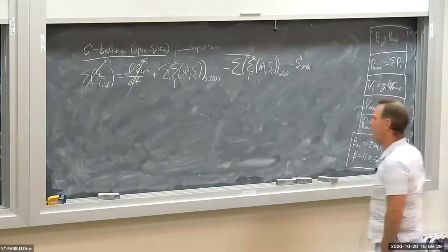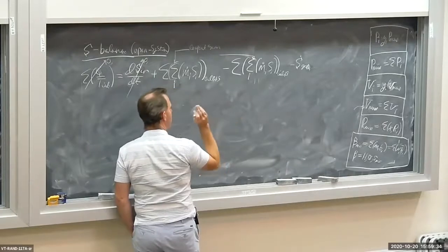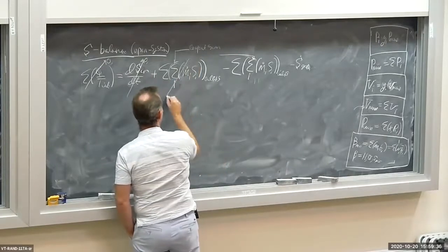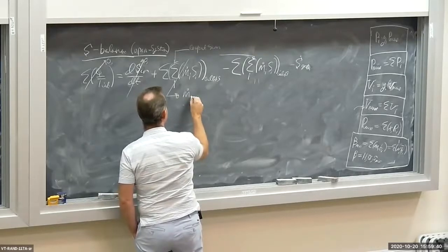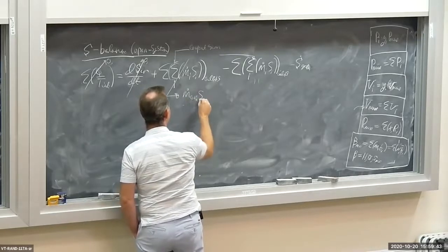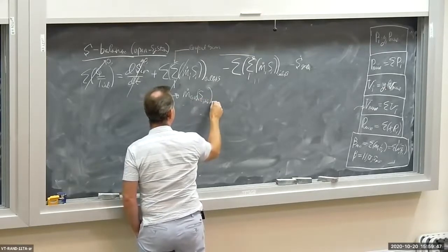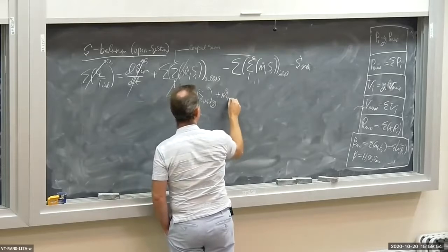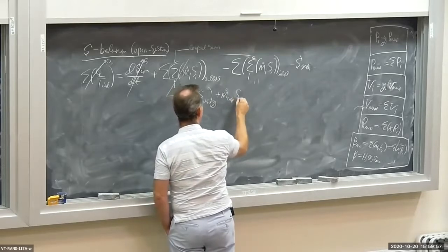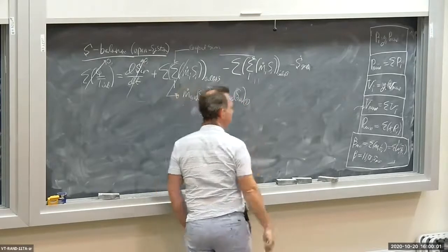Let's attack these summations here. I have one outlet, but I got two species flowing across the outlet. So I have M dot C2H6, S of the C2H6, evaluated at the outlet, location 3, plus M dot CH4 times S CH4, evaluated at the outlet.